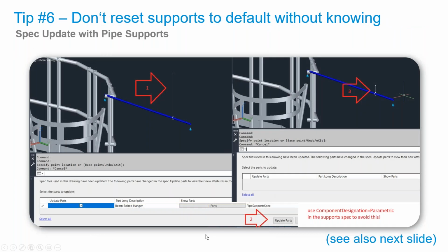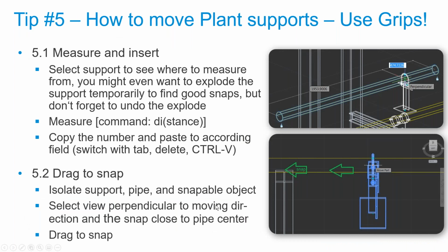And one thing to note also is that if it ever does become disconnected, you'll see the little water droplet that's up there, like you see at the end of that piece of pipe. The supports will show the same disconnect graphic there. So sometimes when you're moving supports, you'll accidentally move it off of the center line or disconnect it. All you got to do is just reattach the support, as long as you are still on the pipe or component.